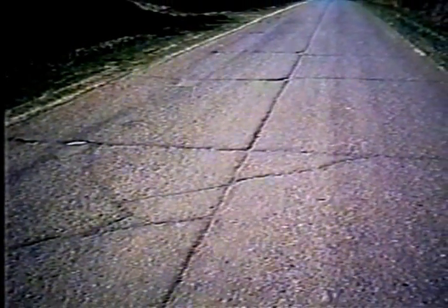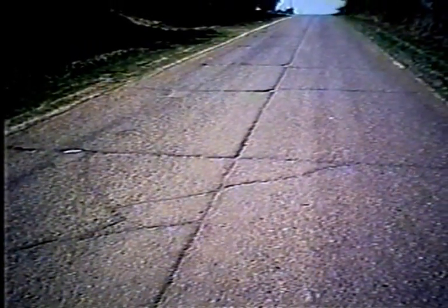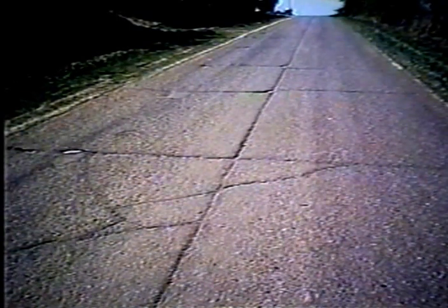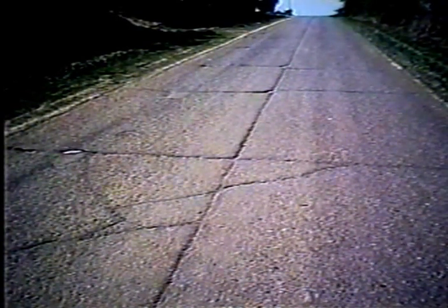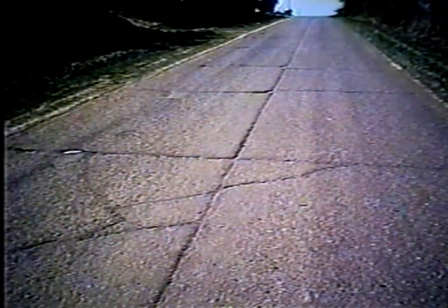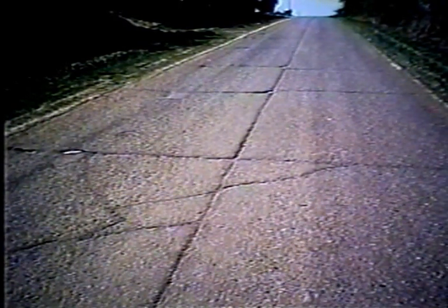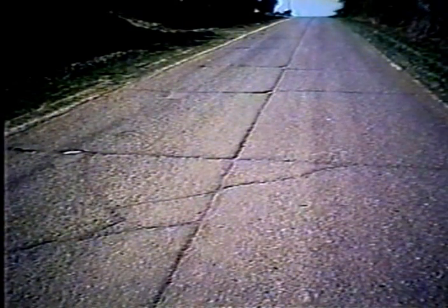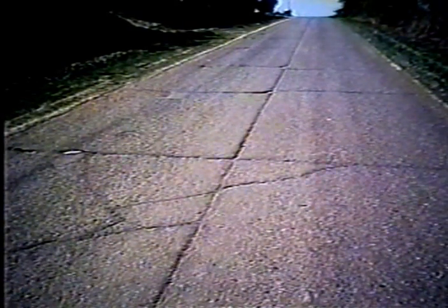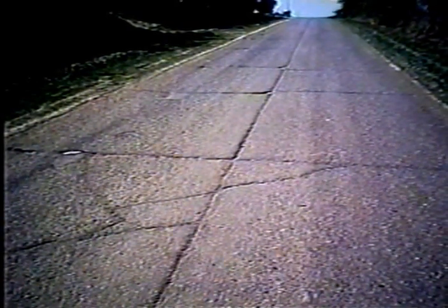Here's another kind of cracking pattern. If you look closely at this slide, I think you can see that you've got an asphalt overlay with some age on it, but underneath is a concrete pavement. You can see a little bit of the curb sticking up on either side. Here what you're seeing is the joints and the cracks in the original concrete pavement reflecting up through the asphalt pavement.